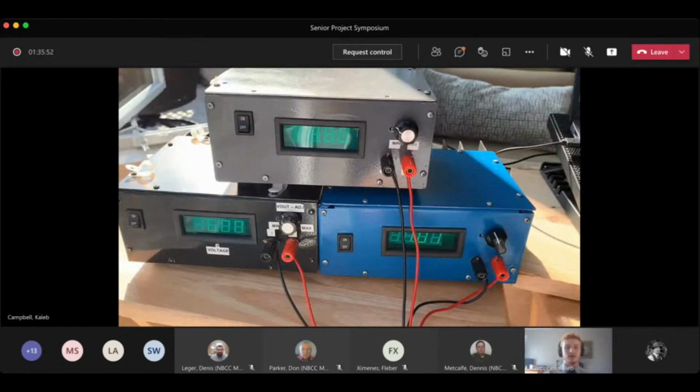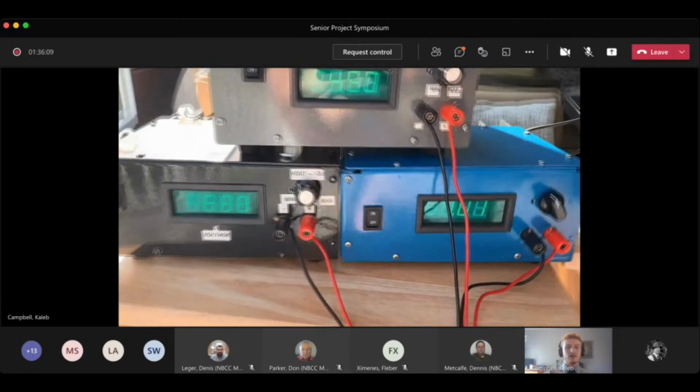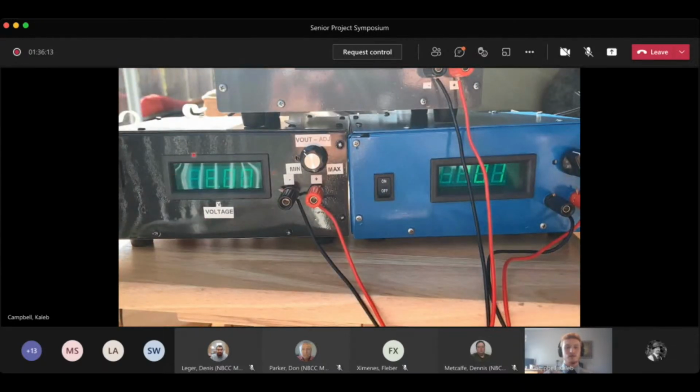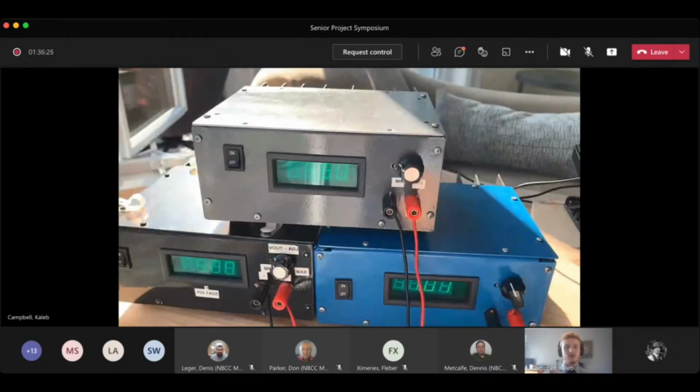So these are the power supplies. This is power supply number 1, 2, and 3. It's really hard to see, but the voltage applied as listed in the calibration is 6 volts for power supply number 1, and 7, as it is here, it's 7.01 volts. My mistake, the value of the voltage output for power supply number 2 is 4.5 volts. When I stated before that it would be 5 volts fixed, it operates the same, as I said before, the TMP36s operate between 2.7 and 5.5 volts.